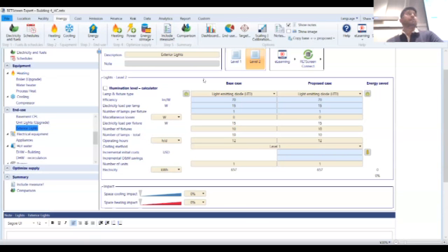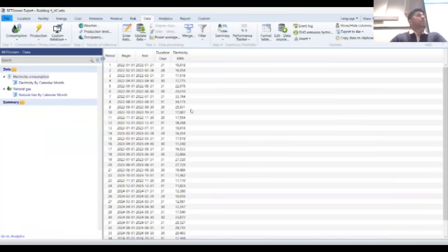It involves regression analysis, and I'm going to quickly show you how. So we've covered the location, facility, and energy tabs. I'm going to jump to the data tab on the top. In the data tab, going back to Hardeep's presentation, if you've synced it with Portfolio Manager, if you use ESPM Connect, it will sync data from Portfolio Manager to RETScreen, and you will see data in the data tab for all historical years and up to the most current data until you sync it again, and it'll refresh the data. So this should be auto-populated if you've synced Energy Star Portfolio Manager to RETScreen.